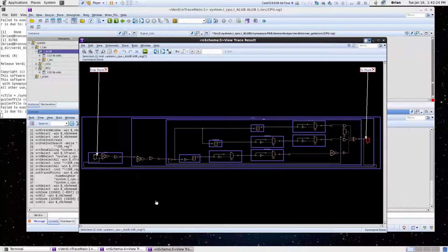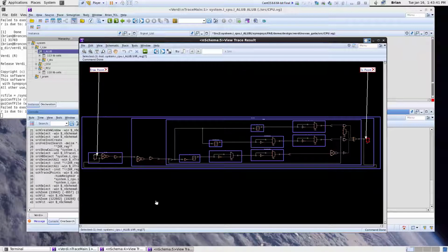So this confirms to me that this trace does cross multiple levels of hierarchy. And then I can use this for analysis to understand what's going on in this path, or if there are things that I need to debug deeper into, like a timing problem, a functional problem, and so on. But the key thing here is that by using the Trace 2 Points trace, I can quickly isolate all the logic between 2 points in the design, either for a gate level netlist or an RTL design.